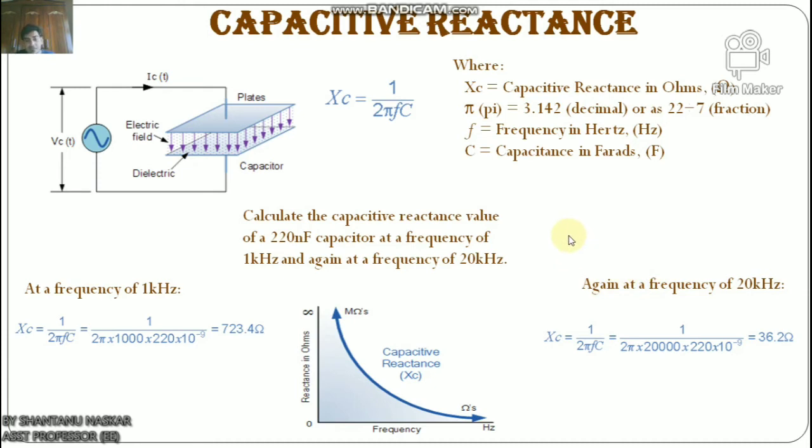Complex impedance exists because the electrons in the form of an electrical charge on the capacitor plate appear to pass from one plate to the other more rapidly with respect to varying frequency. So as the frequency increases, the capacitor passes more charge across the plates in a given time, resulting in a greater current flow through the capacitor, appearing as if the internal impedance of the capacitor has decreased. Therefore, a capacitor connected to a circuit that changes over a given range of frequency can be said to be frequency dependent.